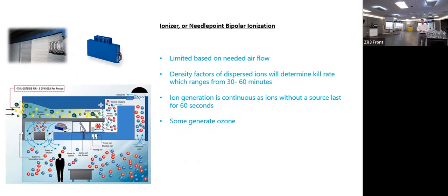There's a lot wrong with this technology when applied in the wrong setting. These are designed to be at the coils of the HVAC system or even at the filter, the MERV 13 filter, MERV 7, MERV 8, whatever you've got in your air handling unit, and it works at the source of contamination. It's not going to clean the air you breathe.